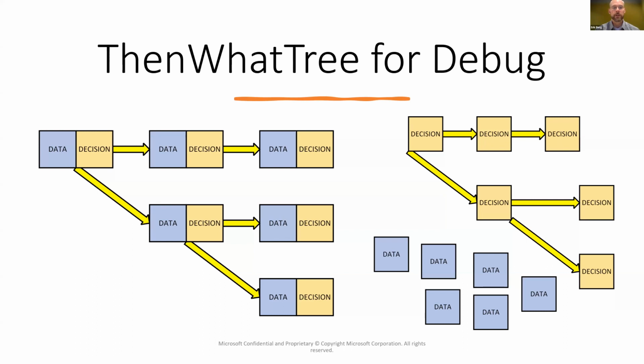And what became clear to me was that debug, regardless of the platform, regardless of the IP, regardless of the flow, can all be represented as decision trees. And a lot of times the decisions in the decision tree are platform agnostic. The only thing that separates debugging PCIe at the IP level in simulation from PCIe in silicon is just the data that's available to you. But I got very good at debugging and representing the flows in these very granular decisions. And it's a good analogy for what we want to do with generative AI.